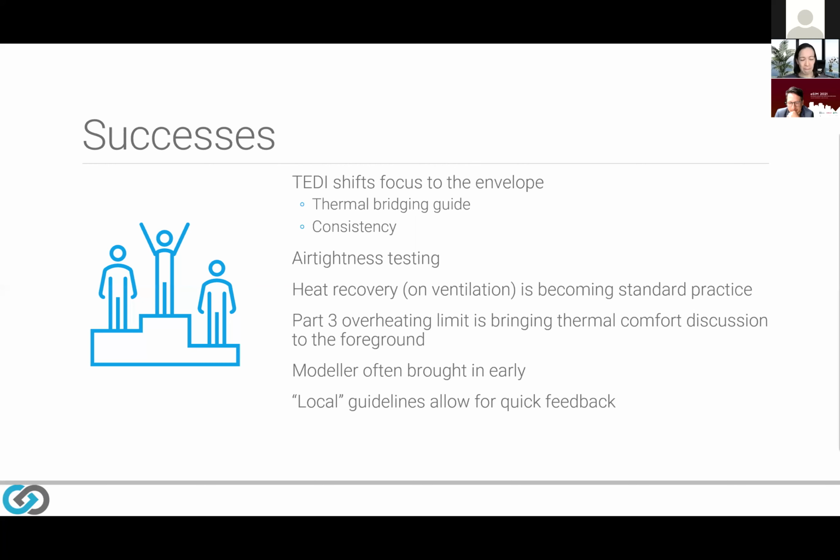Another item that I haven't touched on as much yet is the Part 3 overheating limit. So looking at that summertime internal temperature and whether it's remaining within a comfortable range or not. That limit is really bringing the thermal comfort discussion to the foreground, and that's having a few implications in future research work that I'll talk about in a couple of slides.